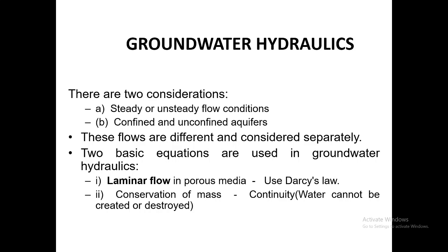So these are the conditions which will be considered for groundwater movements, based on the hydraulic and geological formations. We have already studied two considerations: steady and unsteady flow conditions, and confined and unconfined aquifers. And then two basic equations will be used: Darcy's law and the conservation of mass. So these are our tools to determine and make the groundwater flow equations.